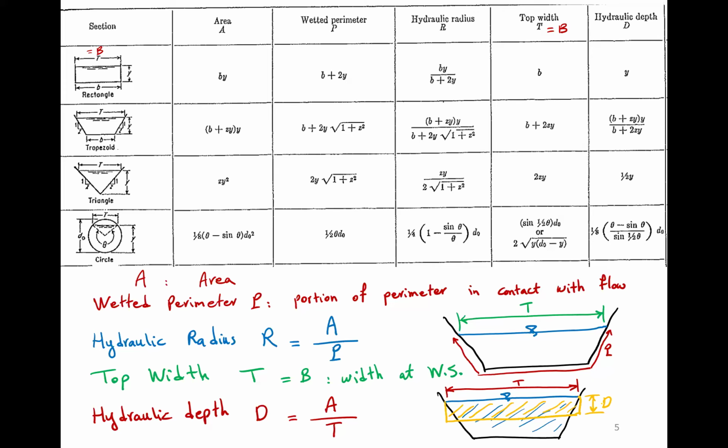In other words, it says, if I want to replace my non-rectangular channel with a rectangular one, what is the depth of that rectangular channel? What is the equivalent depth? So it's a definition. It's not a physical dimension.